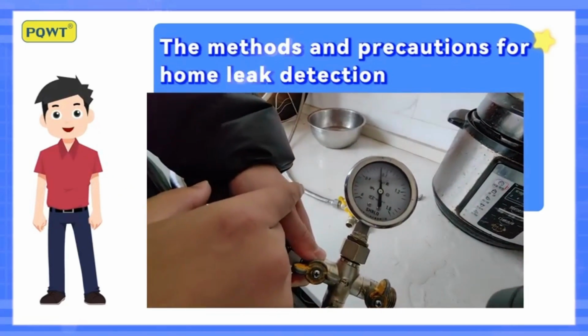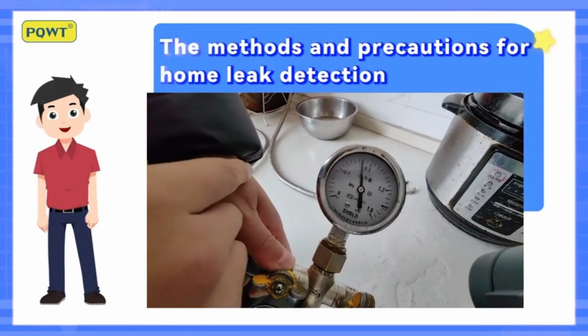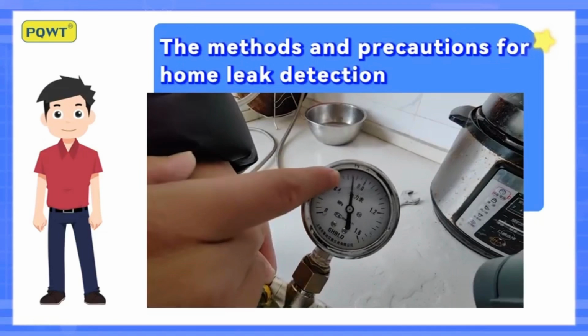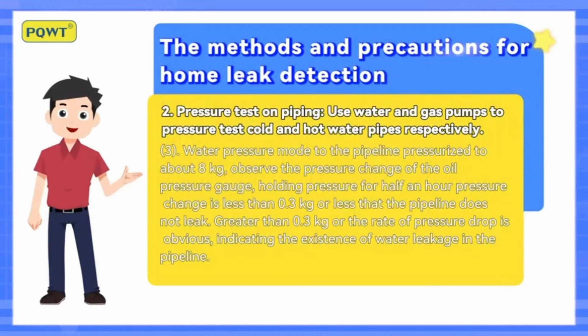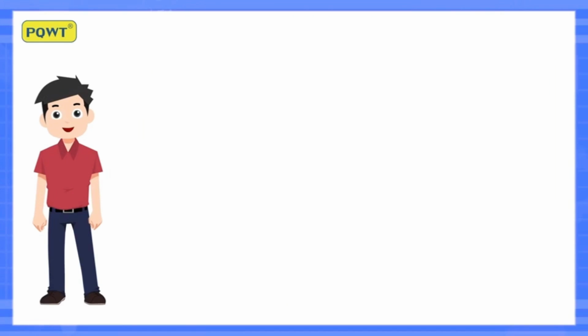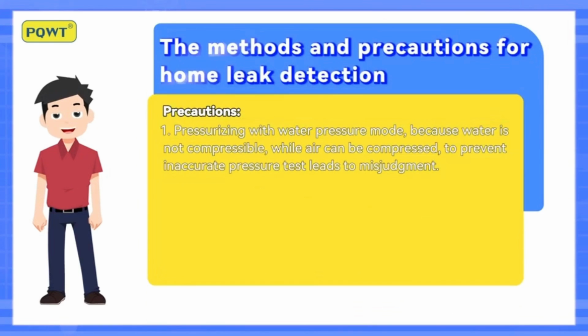3. Use water pressure mode to pressurize the pipeline to about 8 kilograms. Observe the pressure change of the oil pressure gauge. Holding pressure for half an hour, if the pressure change is 0.3 kilograms or less, the pipeline does not leak. If it is greater than 0.3 kilograms or the rate of pressure drop is obvious, it indicates water leakage in the pipeline.